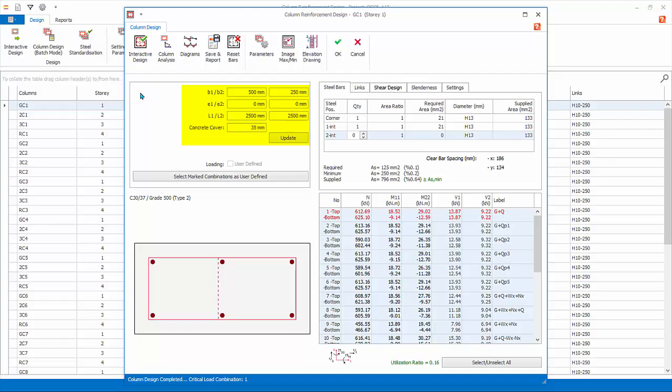size works. However, due to the change in column size, the weight and stiffness of the model will change. Hence, you should rerun analysis to derive new design forces and recheck the column design to ensure the design is sufficient finally. The column design forces are automatically linked and updated to the latest analysis run. You can overwrite the column design forces manually using the user-defined combination function.